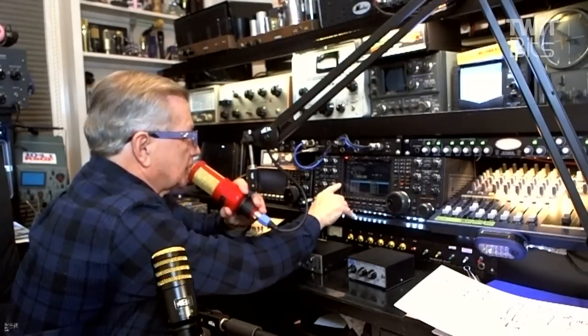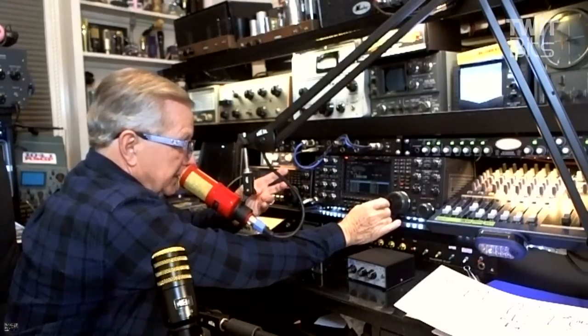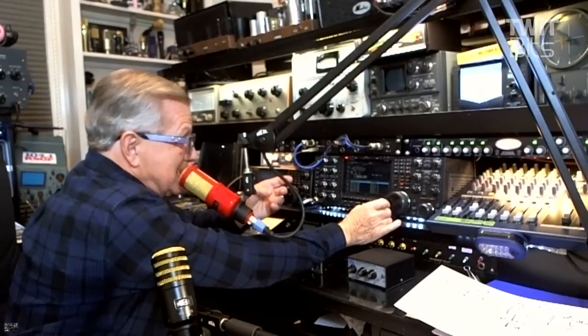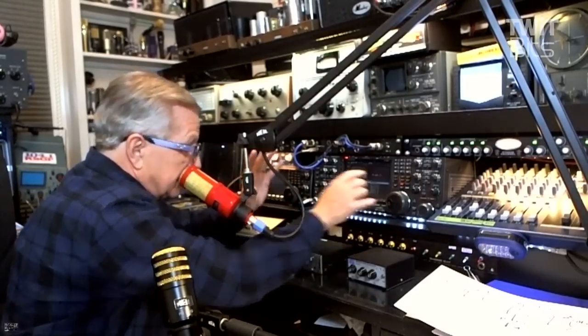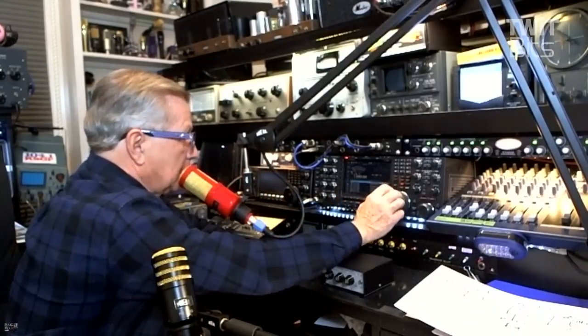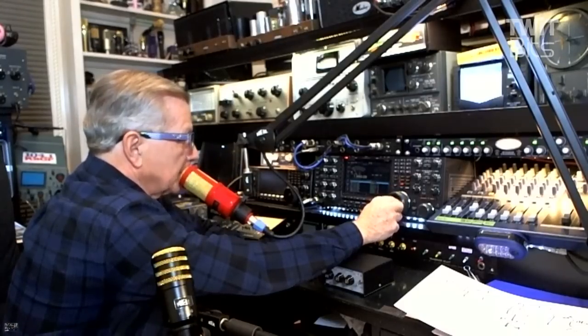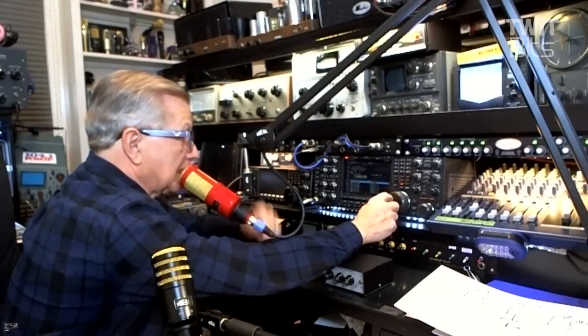Well, let's go to the next step. This is 2.4. This is what most of the transmitters have in them, especially like the 480, the 7200. These are late models, and it's kind of sad that they didn't do a little better with that. And that's not to say it's a bad transmitter, but that's just where they set the filter, and you're going to be having to suffer with that. Here we go again. If I increase the bass, it doesn't make much difference because all of that's rolled off. That filter's rolling off the low end and it's rolling off the high end.